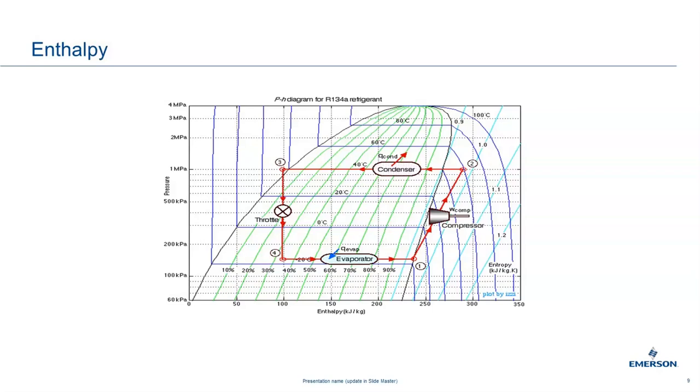If this wasn't written here, just remember it's your condenser, and it's where we're rejecting that heat that we talked about earlier. When we hit point three there and go down vertically, we're talking about our metering device, all right? So we're coming back here, going into this, we're coming across, this is where we're absorbing that heat, this is our evaporator, okay? So on this side is our liquid side, and this side is our vapor side.